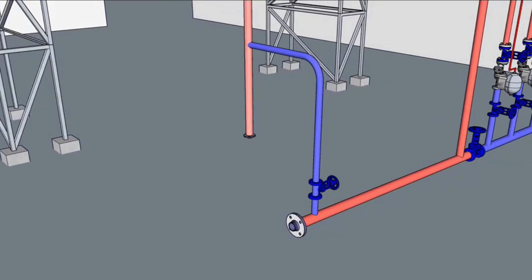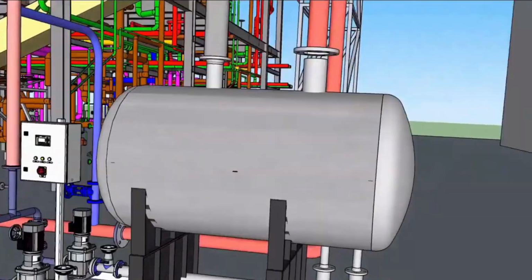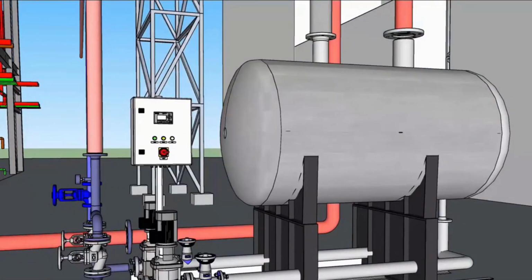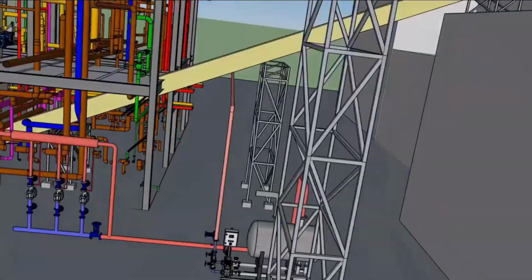To negate this, a new design based on the loads of this section of the plant was implemented, incorporating a condensate receiving tank with a duty standby electrical pump set. This simple action saved the plant €36,570. CoolPlanet OS fulfills many functions, one of which is the ability to uncover optimization opportunities while giving the client all of the necessary feedback required to make a confident decision on the feasibility of these opportunities.